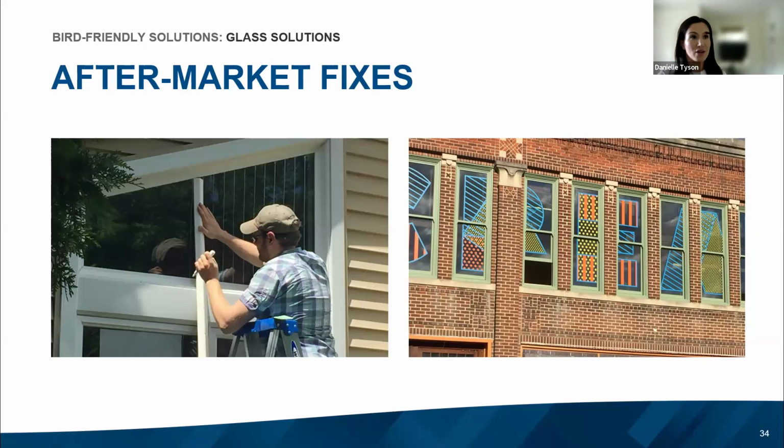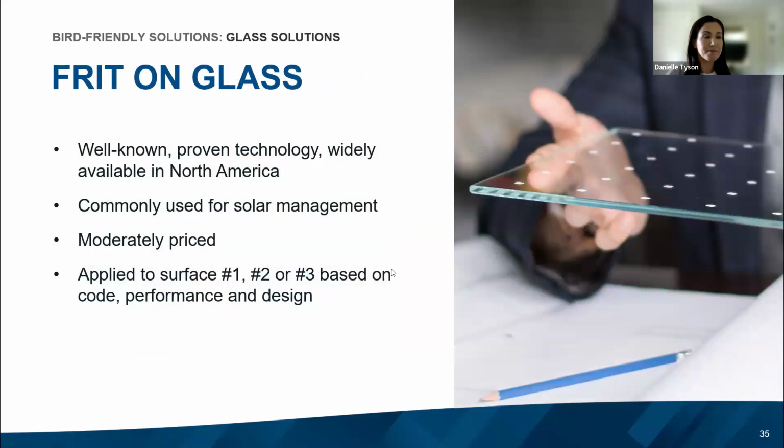They are bird friendly. They're on ABC's website and they score a 1. So we need to be 30 or lower. A 1 is really good. So there are plenty of aftermarket fixes. But when we're talking about more permanent solutions, long-term solutions for bird-friendly glass, I mentioned ceramic frit before. This is our baseline, most visible, but typically least expensive solution for bird-friendly glass: a ceramic paint permanently fired onto the glass in a specific pattern.